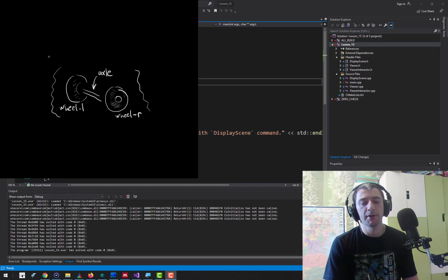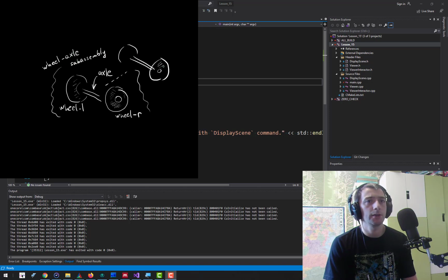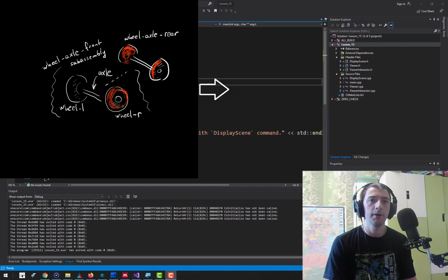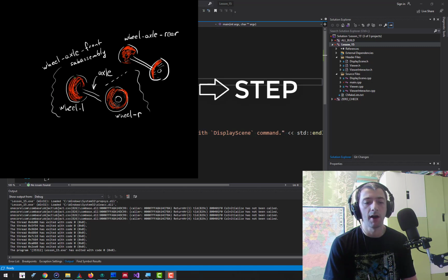The idea is that we design something simple, we prepare some simple object hierarchy containing some simple cylindrical primitives to represent this car chassis, which we've been talking about in one of the previous lessons. And then we try to associate different colors and names to different components and export this whole thing to a STEP format, to a STEP file.